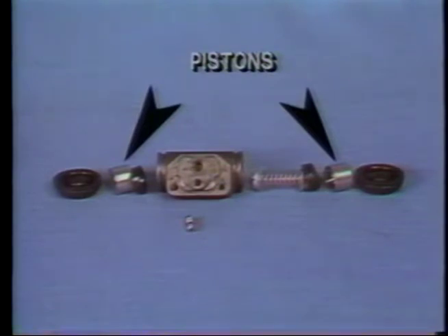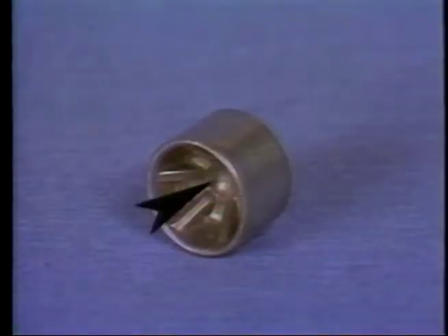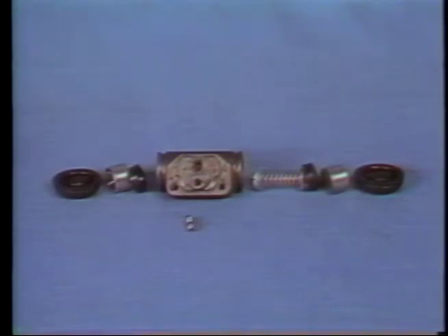For this question, refer to the corresponding graphic on your mini-test. In the illustration shown, which component is not installed correctly? A, the wheel cylinder cups, B, the wheel cylinder pistons, C, the spring, D, the dust boots. The wheel cylinder cup, spring, and dust boots are installed correctly. The pistons are not. The indentations in the pistons are seats for the push rods, which should face toward the outside. The correct answer is response B.